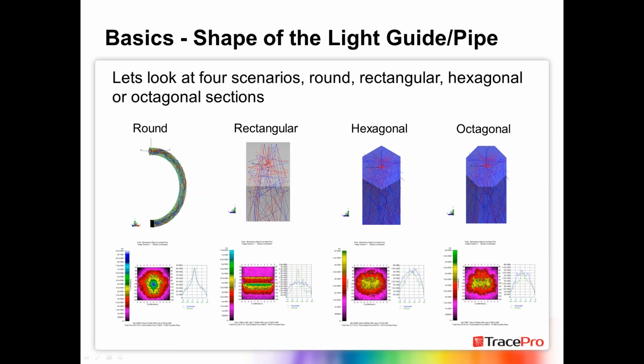And if it's a long pipe, you may get very little light out of that end, but you should get the same uniformity. In fact, you should get a very good uniformity if you've got an exit surface texture on that particular light pipe. So really 3D printing can be disastrous, or it can be very close, depending on what the shape is and how long it is.